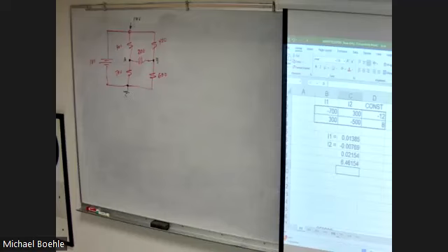How many can I actually write an equation for? In other words, how many of those currents have resistors between 2 poles? 5. Only 5, exactly, right? Because the current in the 10-volt source, there's no resistor in there. There's nothing I can use to figure out what that current is.